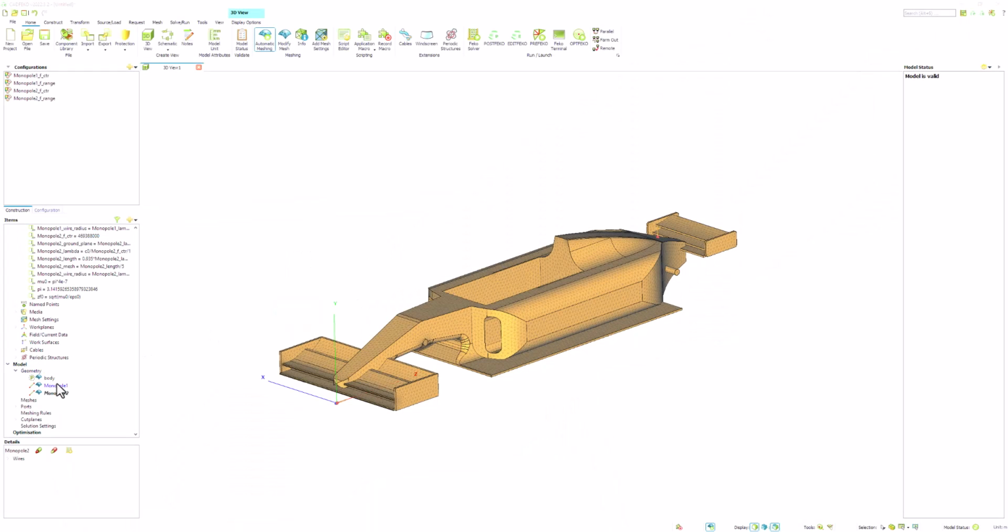Since we know where these antennas should go based on our initial design stages, we can easily edit the geometry to move them to their appropriate spots. We must simply define the start and end points of the devices, which is made easier by the automatically created variable defining the antenna's length, which was created from the component library.